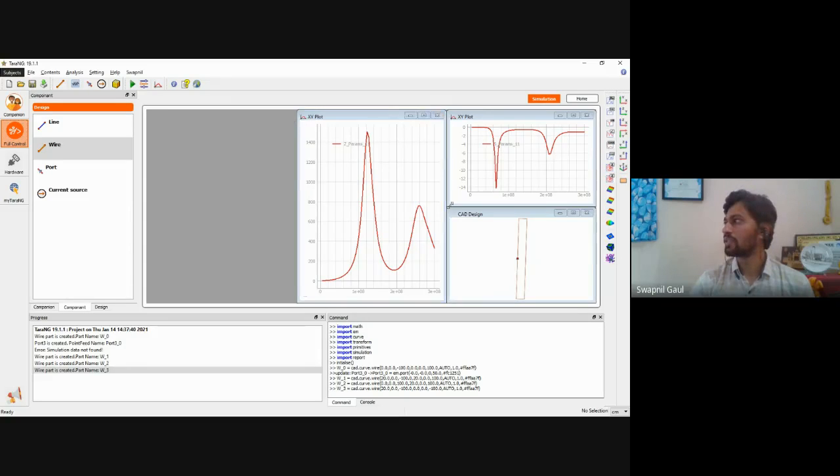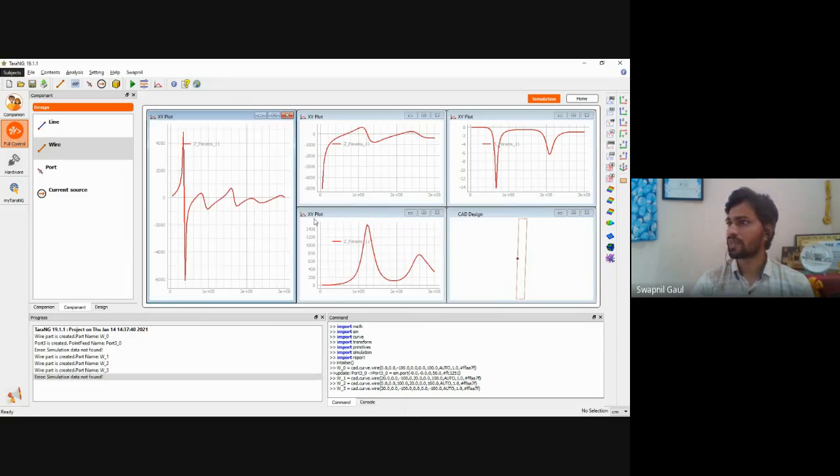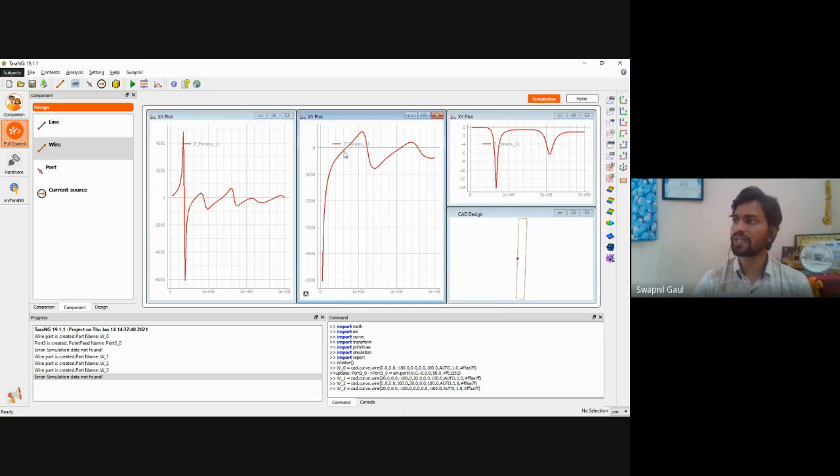Now we will see this imaginary part. In the imaginary part, if you compare these two plots, here it was capacitive, but now this is a shorted cable. When we have a shorted cable, it is going to behave like an inductor. In this case, we call this a current radiator. The earlier case, where we simulated the dipole antenna, is like a voltage radiator.